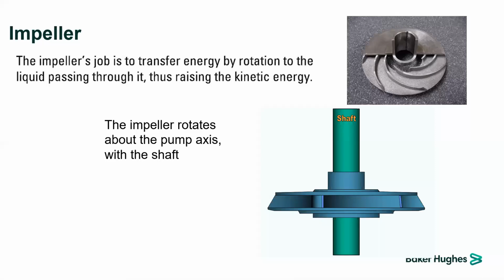This impeller rotates with centrifugal force on the production fluid, and the fluid goes through the impeller and then to the diffuser in order to create kinetic energy, which goes to the second impeller, as shown on that schematic, by rotating the shaft. So it provides centrifugal force to the fluid and gives that kinetic energy to the next stage.